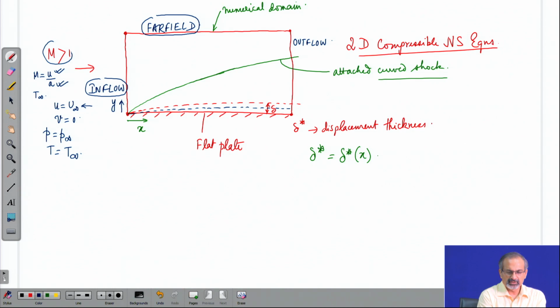We are not going to use a very high supersonic Mach number, which brings in conditions which are hypersonic in nature, but it could be a fairly high supersonic Mach number, so that the thermal effects in the flow also become perceivable. That means, there is viscous dissipation in the boundary layer, which shows up in the heating of the boundary layer region and so on.